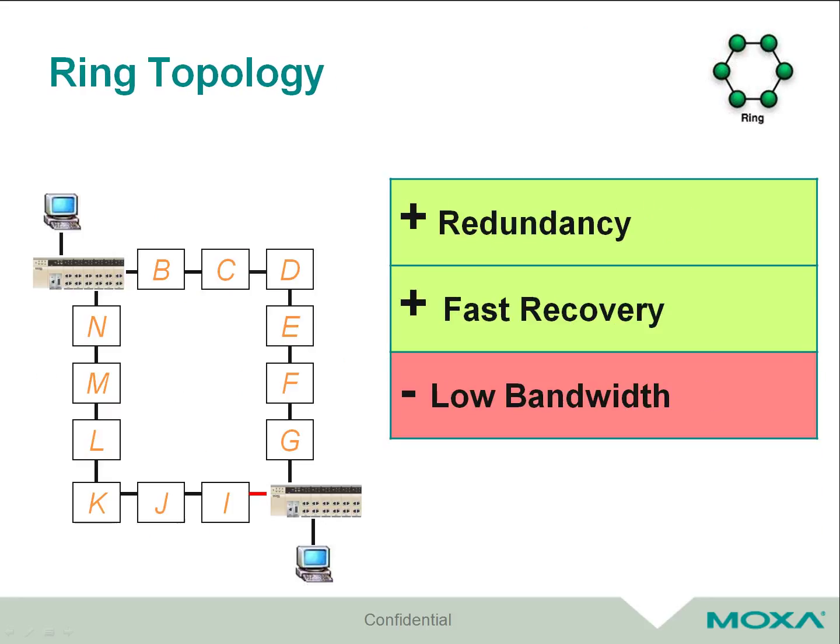The best recovery time could be achieved in a ring topology. It has redundancy capability and simplicity at the same time. The disadvantage is still low bandwidth because a ring is kind of a looped bus topology.